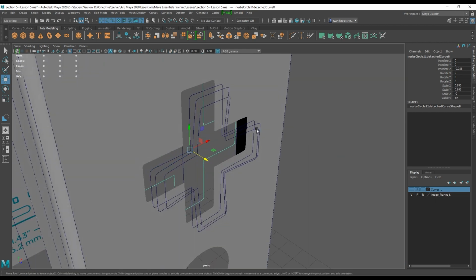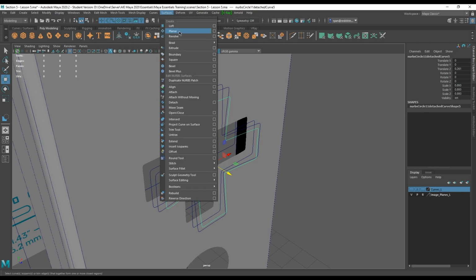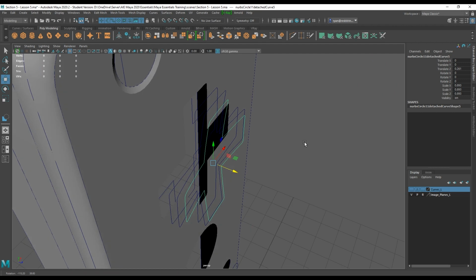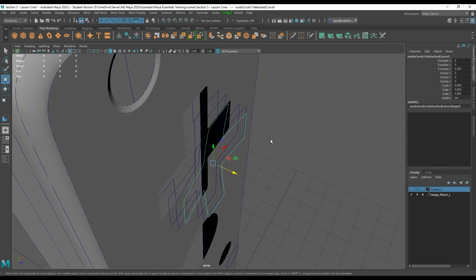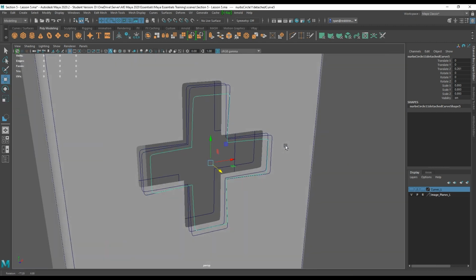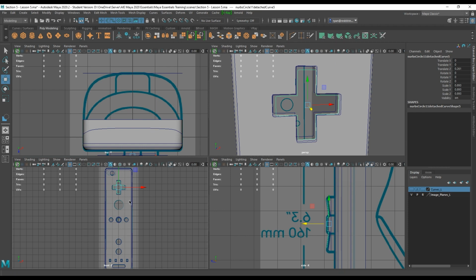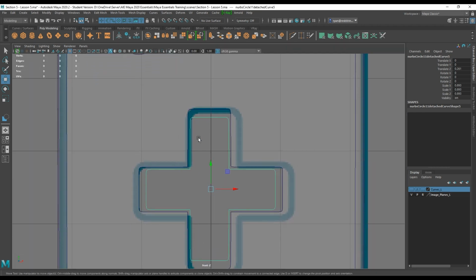So the first one, I'm going to go surfaces, planar. It doesn't seem to like that because of the non-straight curvature. Maybe if we make this straight and then do the bend after the fact. Okay, now let's see if this concoction works. So now from the front view, I can see that the tops and bottoms of this first one don't line up quite nicely. There's a very big gap.